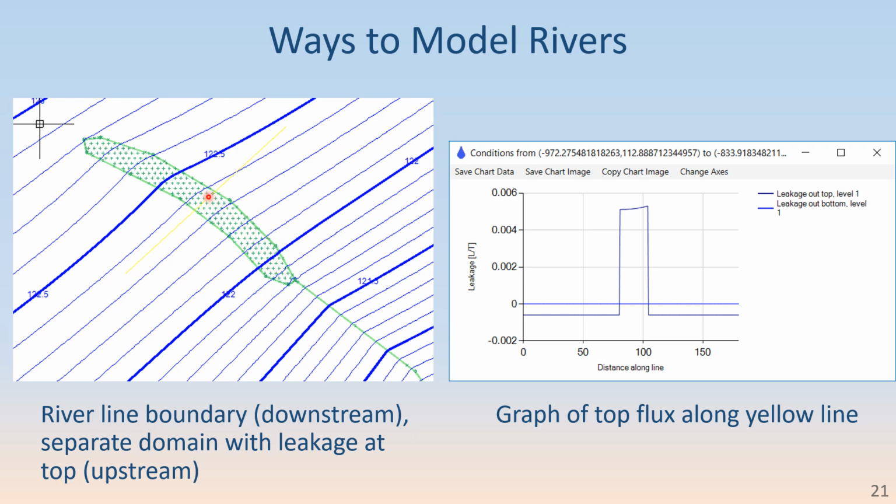And inside that domain, there is a spatially variable area sink that lets water out of the domain and up into this reach of wetland or river based on the difference in head between the underlying domain head and a specified head along this wetland or river. And that specified head can slope and have a curve to it, or it can be constant. And like I said, we'll get to that later when we talk about top and bottom conditions and spatially variable area sinks.